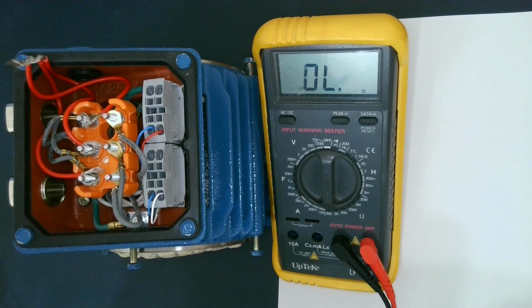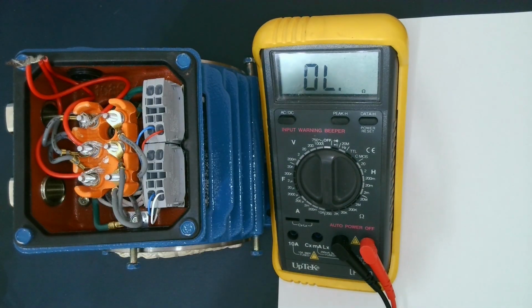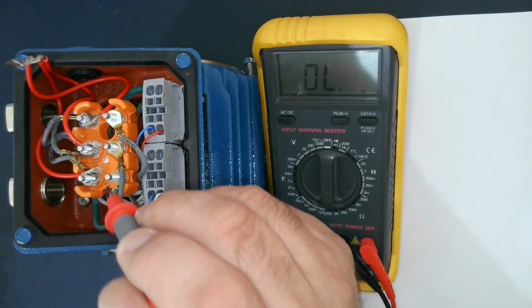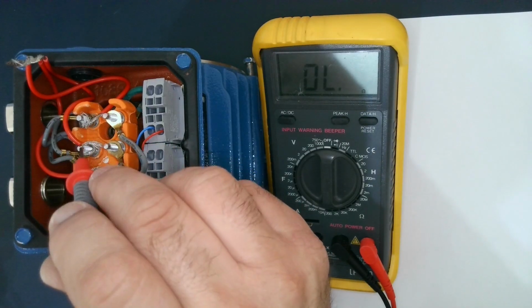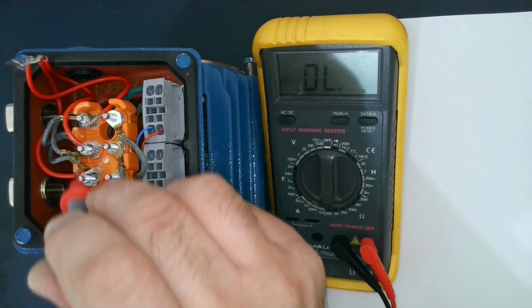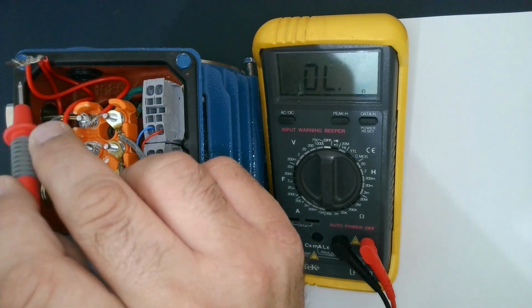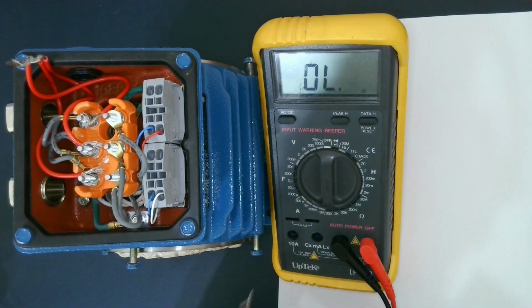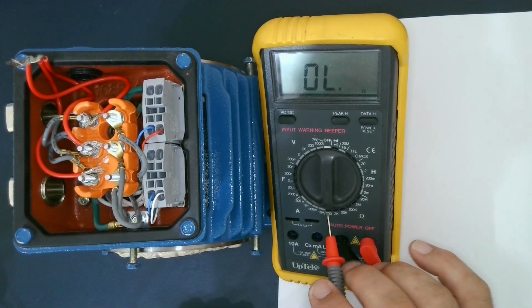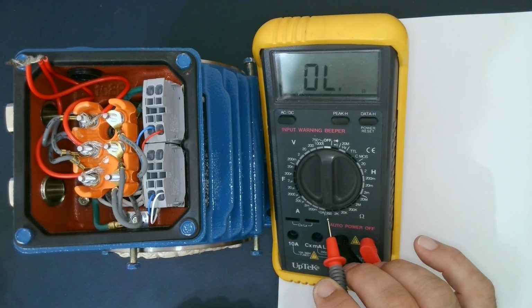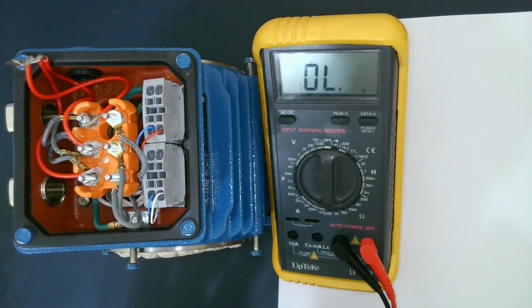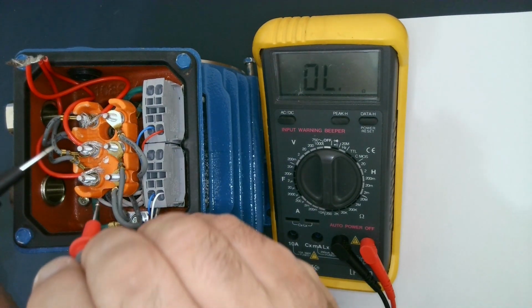What we see here is one of the stators I used before in chapter number 2 to explain the machine construction and the three-phase winding. We have the terminal box with 6 terminals, 1, 2, 3, 4, 5, 6. I connected these 3 points together to make a star point, as we can see here. I'm going to use the multimeter to measure the resistance. I adjusted it for 200 ohm. If we need to change the scale, we can, but I presume the stator resistance is a small value. So I'm going to measure the resistance between phases A and B now.